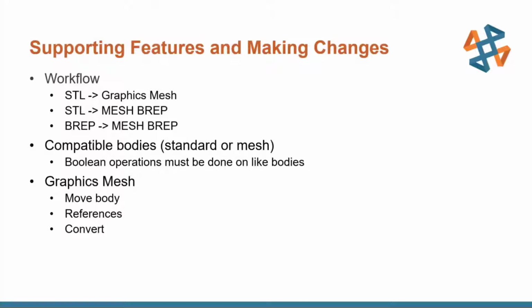And of course, the graphics mesh is a little bit limited in what you can do with it without converting it, but you can move it around. You can create references to it, and you can actually create sketches and create references from that as well.